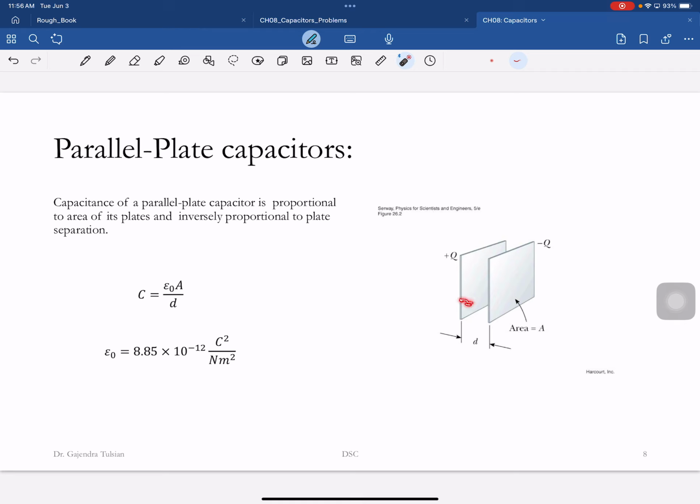So, yeah. The easiest thing to do is fill it with a dielectric, an insulator, let's say a piece of plastic or whatever. Okay. So it gives mechanical support to the thing, or you can do the following. Here's an aluminum sheet, here's a paper sheet, here's an aluminum sheet. That paper gives you mechanical support. In addition, it increases the capacitance of the capacitor.